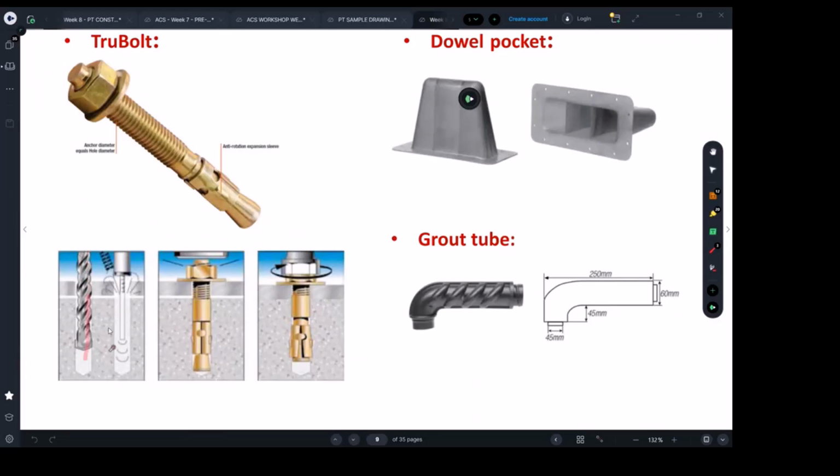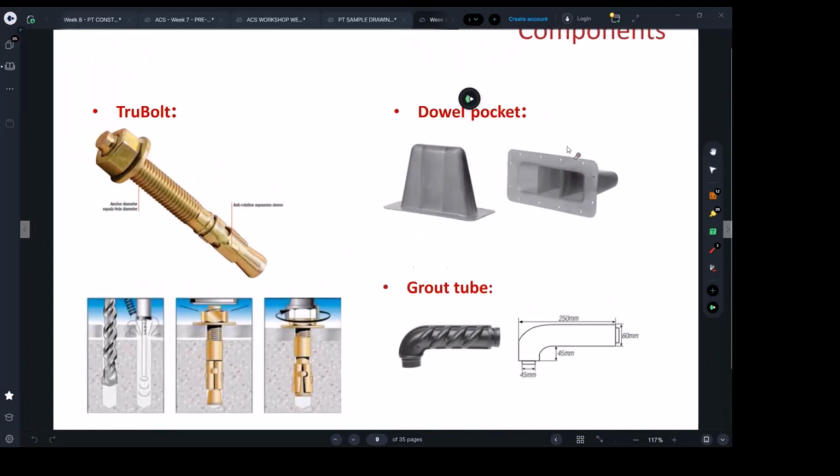You drill a void, clean the void as shown here, and then install your dyna bolts or true bolts. They have different capacities. But the point is, if the ferrule voids were accidentally placed in the wrong position, or it was decided not to use ferrules, you can just mechanically install bolts. That's another option, right?